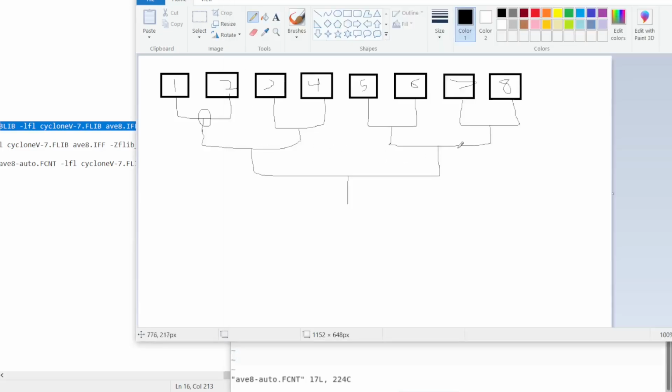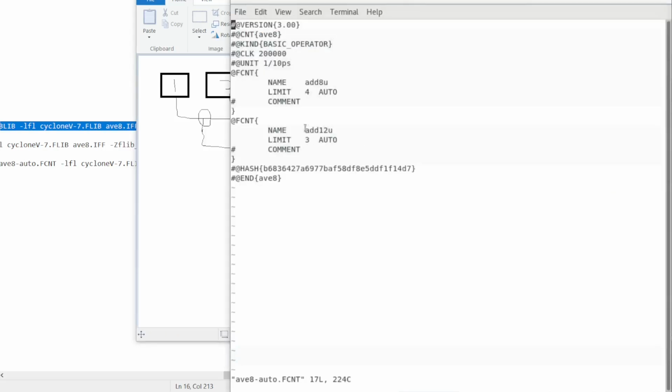And so we need two 12-bit adders. And then next, to add these two 10 bits together, well, we would need a 10-bit adder. However, we do not have a 10-bit adder, so we will instead use the 12-bit adder. So in total, we need 3 12-bit adders.